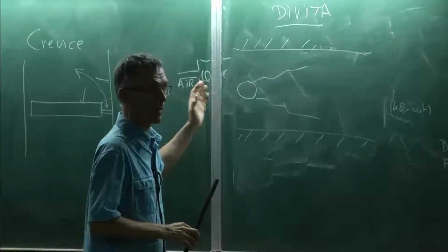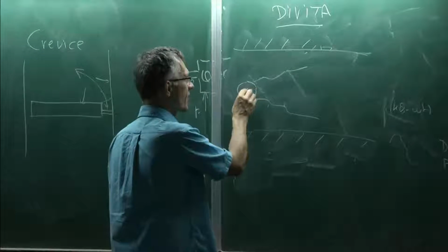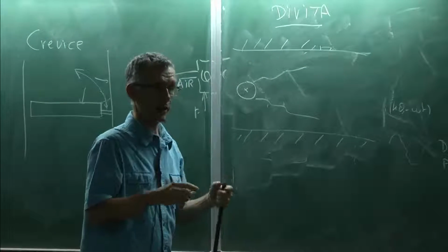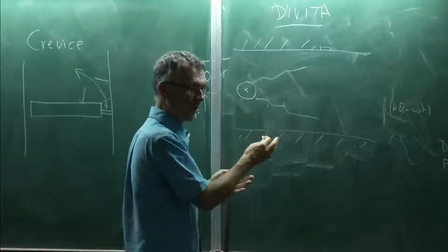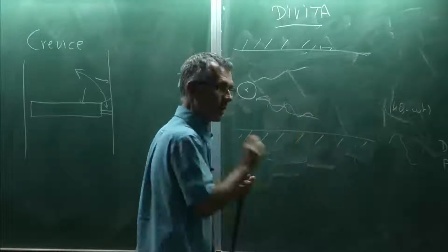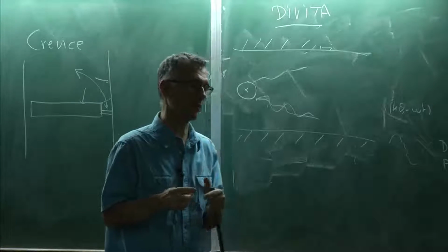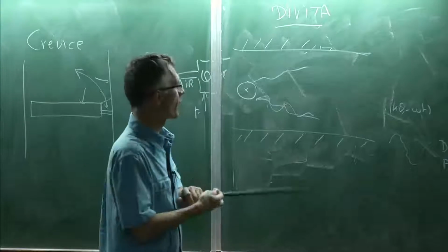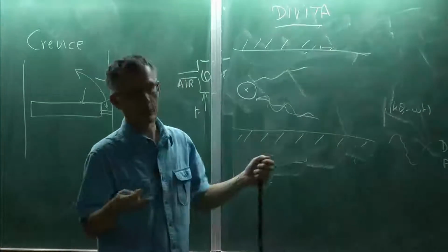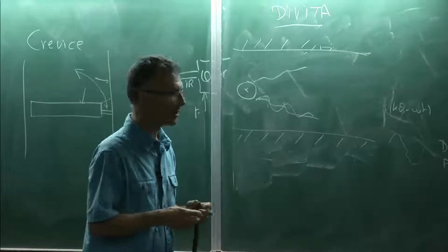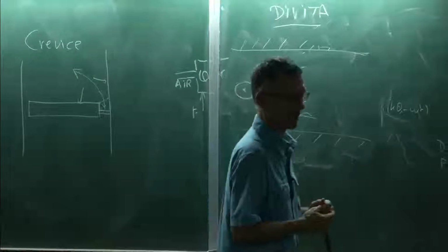If the flame flashes back, it's not. Now, once it is stabilized, it can be either stable, it doesn't move, or unstable, it moves. So flame stabilization is a different problem compared to flame stability. Of course, if you have no flame stabilization, you will not even be able to talk about the flame stability. So you need first to stabilize the flame.